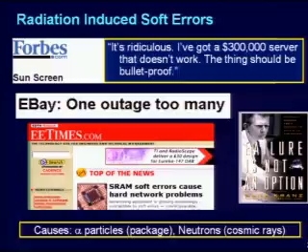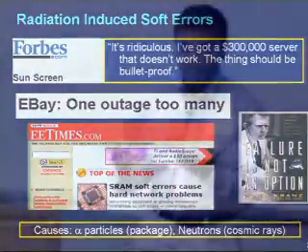So let's say that you designed a system, and let's say we start from a hardware chip, and we perfectly made sure that everything was correct. It was perfectly formally verified, and then it was tested, so there were no defects. And you have this chip in the field, and then you see errors happening left and right in the storage nodes, in the flip-flops, in the memories, in the combinational logic. And one of the big sources of these problems is what is called radiation-induced soft errors that happen because of alpha particles in the packaging material and neutrons that are coming from cosmic rays, basically.